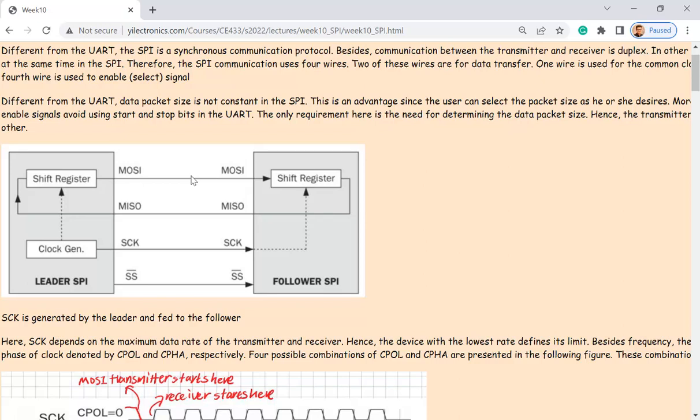It's a serial, right? So 1, clock is 1. This is a chip selection, just 1 pin, high or low. So 0 active, which means if you send a 0 from the leader, it's going to activate the follower. So it's going to do a chip selection. So it's going to enable this follower. And clock, just the clock.